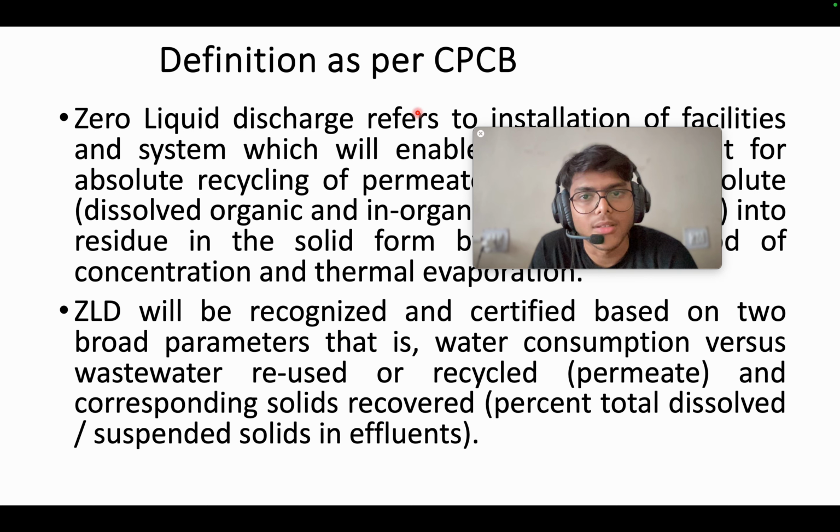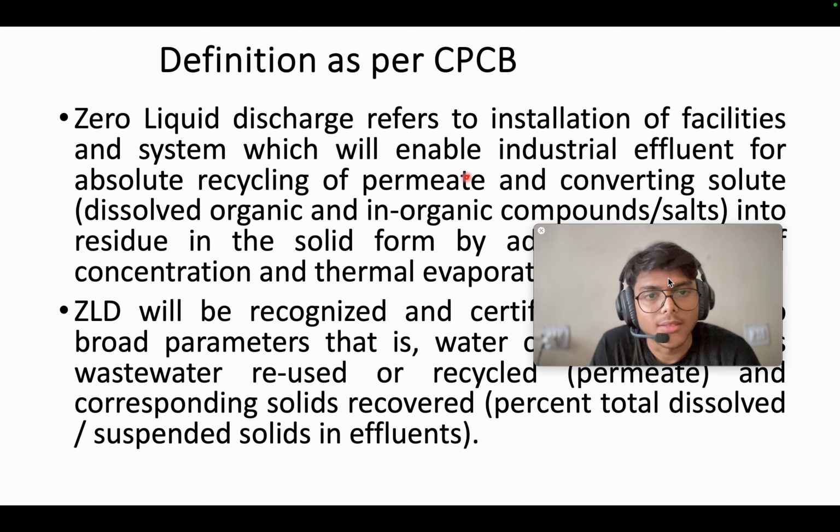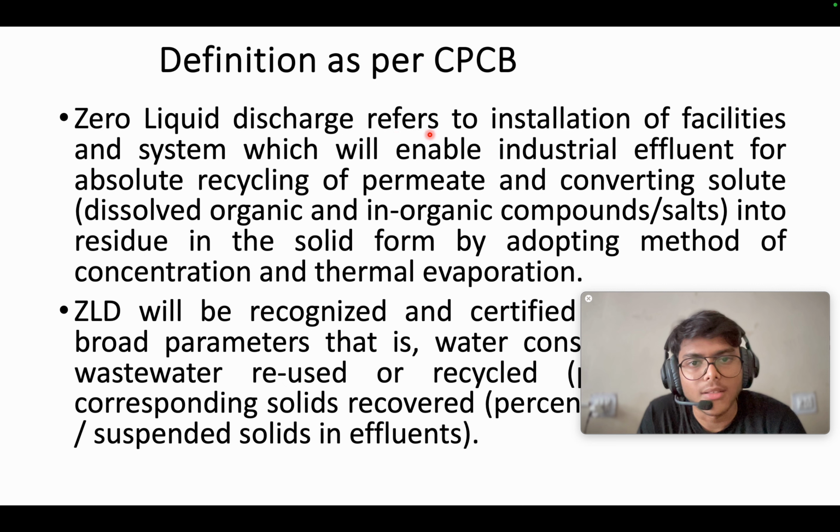Next, what is the definition of zero liquid discharge as per the CPCB? So let's see. Zero liquid discharge refers to installation of facilities and systems which will enable industrial effluent for absolute recycling of permeate and converting the solute, that is the dissolved organic and inorganic compounds or salts, into residue in solid form by adopting the method of concentration and thermal evaporation.